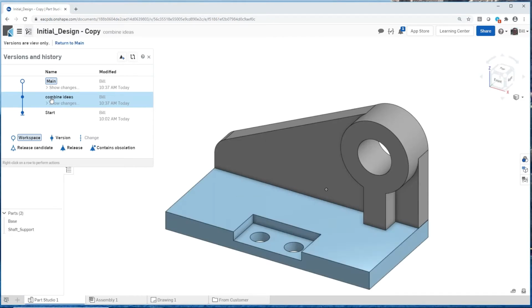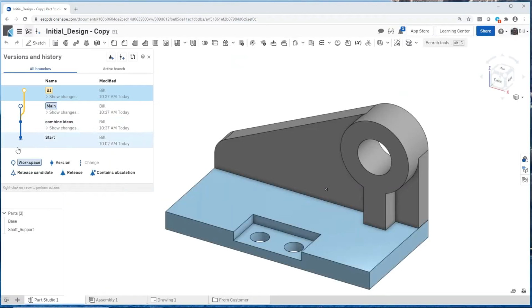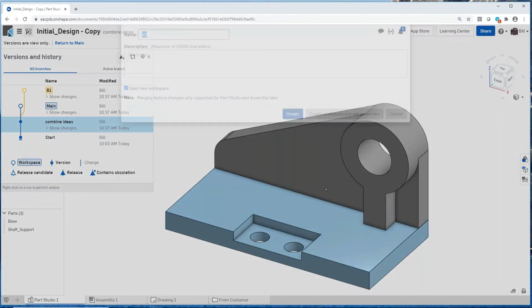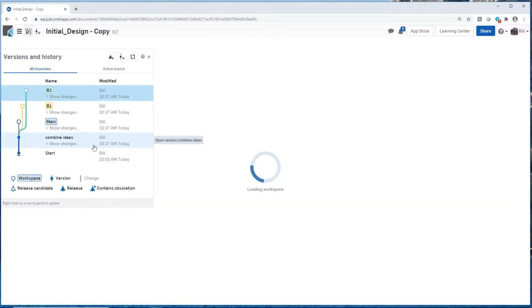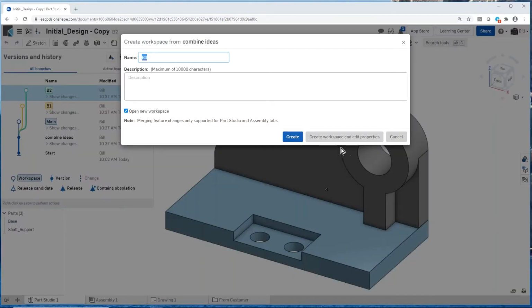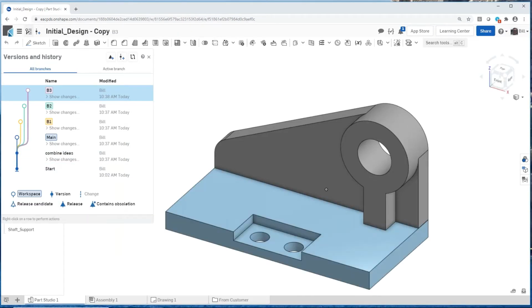At this juncture, I'm going to start generating some different branches, different ideas that can branch off from these two components that we have here. Basically these ideas revolve around combining these two parts together. So I'm going to create a branch, and we'll create branch 1. We can see off the main history tree here, we now have a branch for branch 1. I'm going to go back here and create another branch, and we'll call it branch 2. We're just going to let it give these branches their default names. So branch 3, and I'm going to even do 4. So let's do 4 different branches.